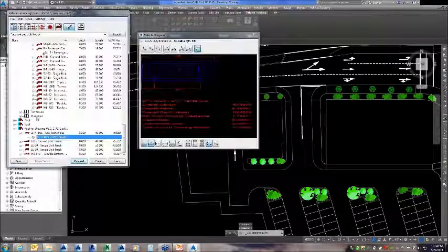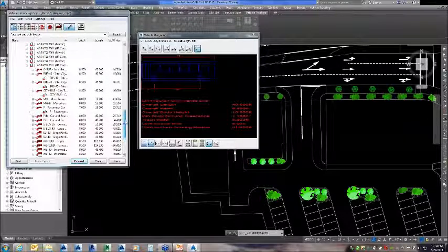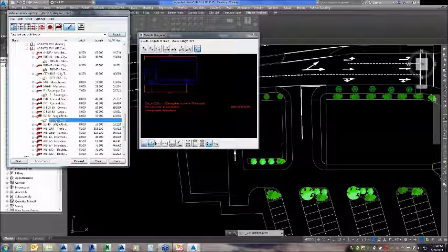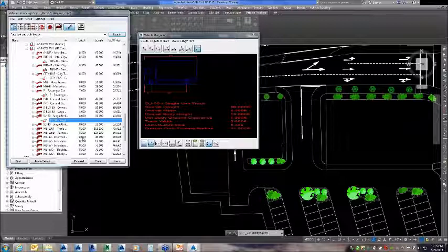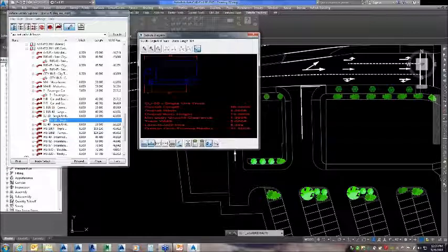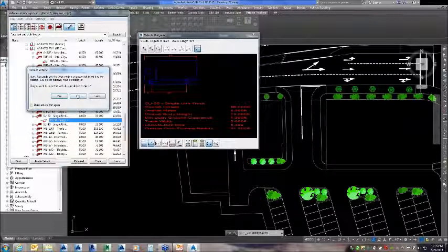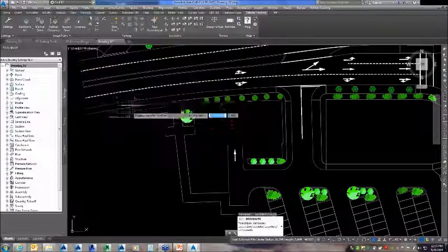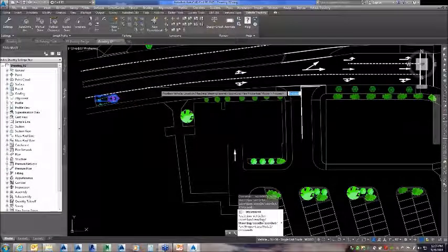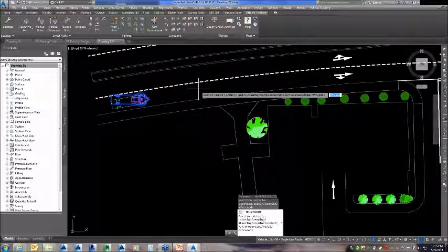And this vehicle that we're going to select, we're going to scroll up, and we'll look at this single unit delivery truck. Something pretty straightforward. And I'm going to select proceed. And again, same thing in reference to clearance and what we want to be able to display. Same thing. I'll select proceed. I'm not going to make that my default vehicle. Then I'm just going to put the vehicle right here. Same thing that I just did in reference to my turning radiuses, I'll just pick right there.